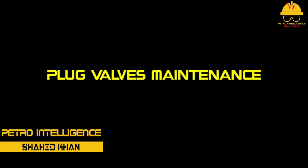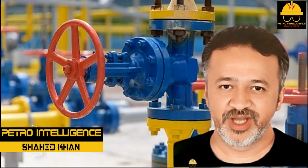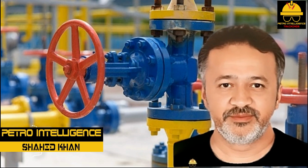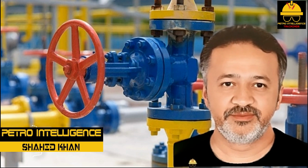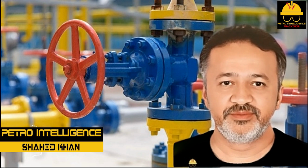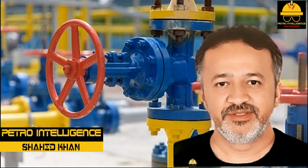Plug valves maintenance. With proper care and maintenance, a plug valve can last indefinitely. Lubrication plays a big part in the life of a plug valve. Plug valves depend on a lubricant inside the body of the valve. This lubricant helps the valve provide a leak-free seal.